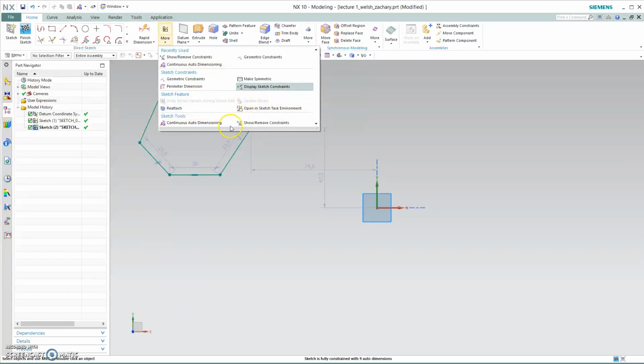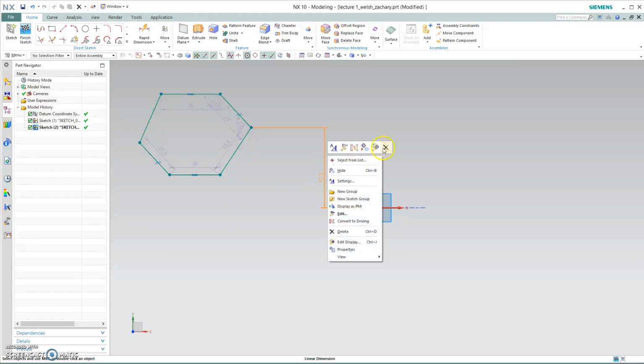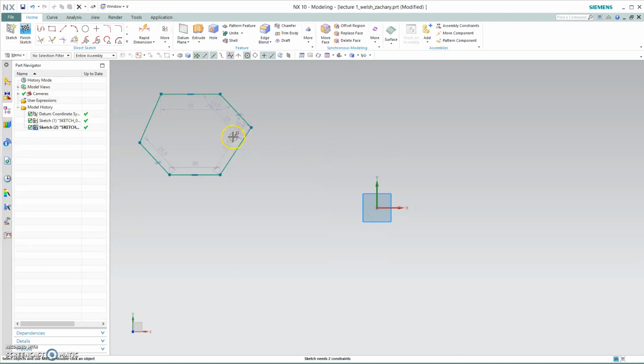You can see because it's not highlighted with this green little box anymore. But these gray ones are still there. That means I have to go in and delete each one manually. Now for this basic sketch, there aren't that many. But if you don't catch it and it keeps going on further and further, it just snowballs into this huge mess that you have to clean up. So what I would recommend is if you started making a basic shape and you notice you have continuous auto dimensioning, just go ahead and erase it and start over.